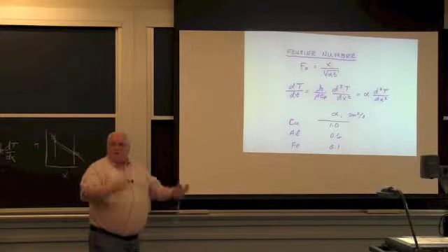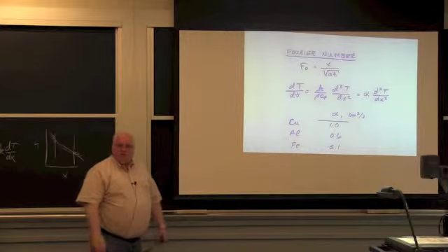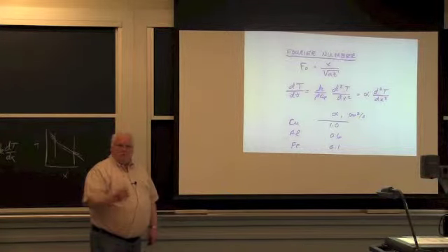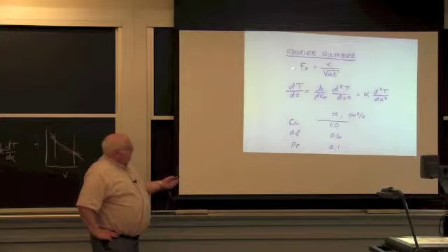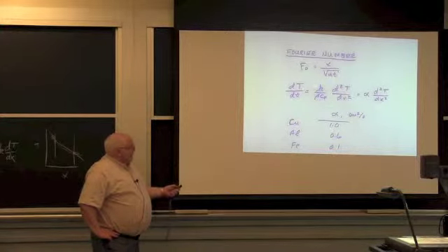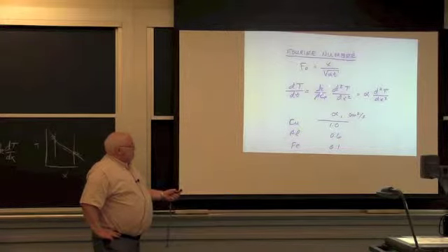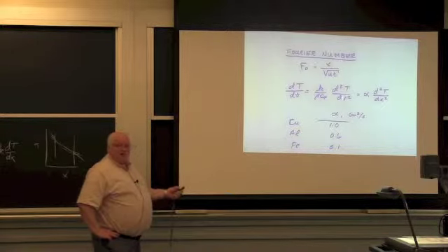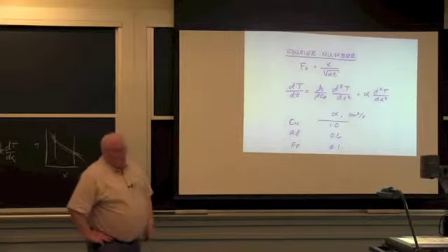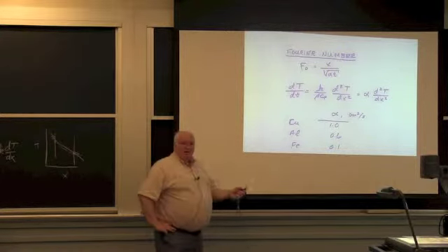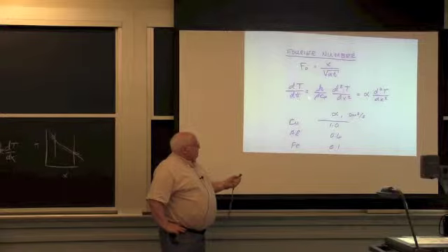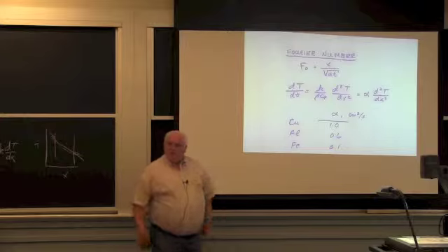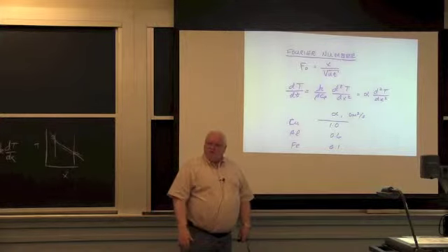And that's what I took over in the math department, the mathematics of diffusion equations. They had a course on it, and there are whole books on it. And it doesn't matter, this is heat diffusion, but you can also look at this as mass diffusion, which is change in concentration with time is equal to the mass diffusivity times the second derivative of the concentration with x. Okay? And if you want to write this down, dT/dt is equal to K over rho Cp times grad squared T. Okay, if you're a mathematician. You guys probably learned that by now, what a grad is. Gradient. Anyway.